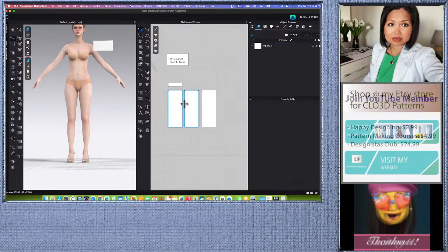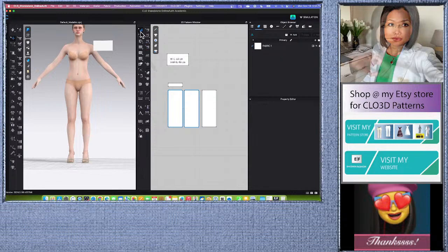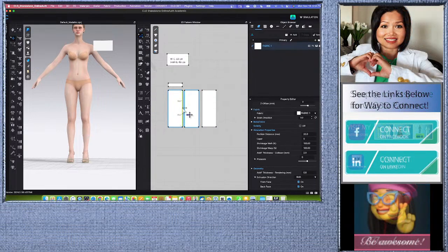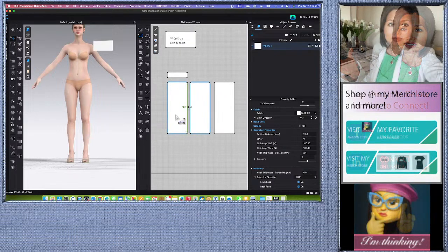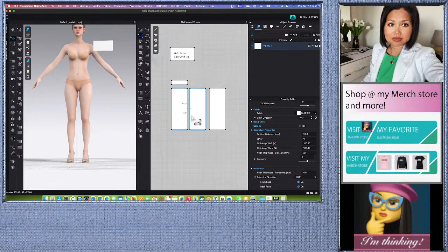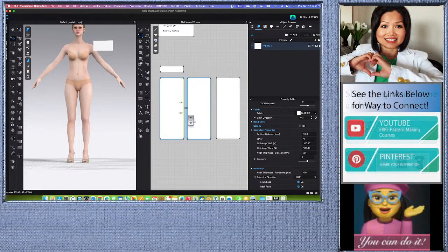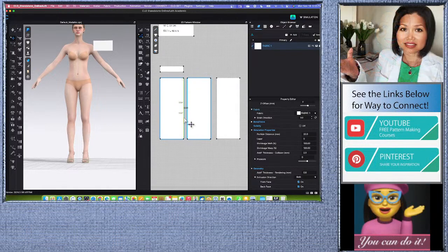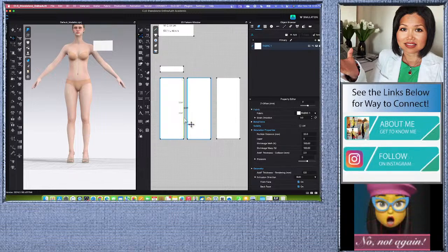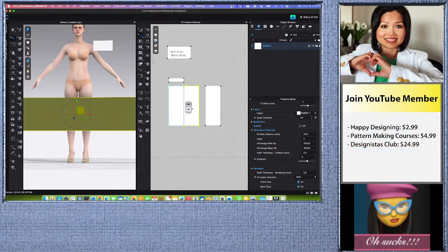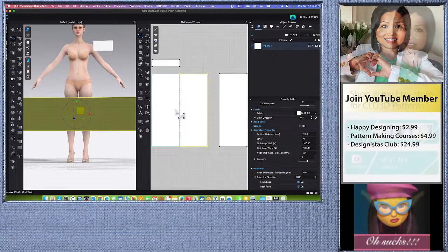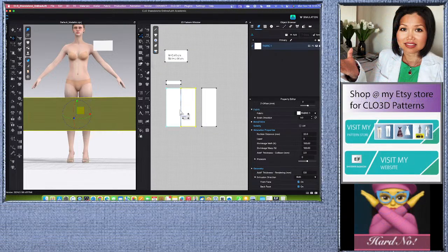Next we're gonna merge them. So I'm going to use this edit pattern tool here, guys, and then click one right here. Alright, so first of all, when I first started doing this, I was so confused because when I merge the pattern together, this time right here I only need to click one, right click and then select merge, and then it fit perfect. It's because they're both linked together, I don't have to select 2.